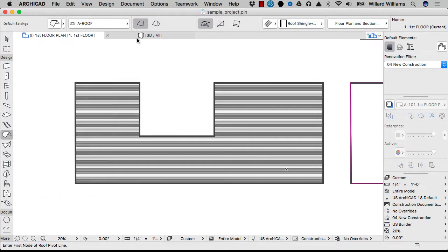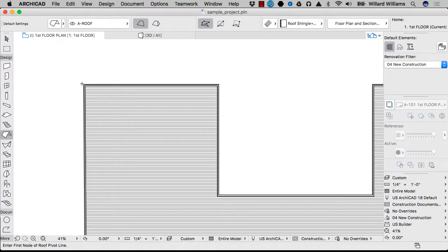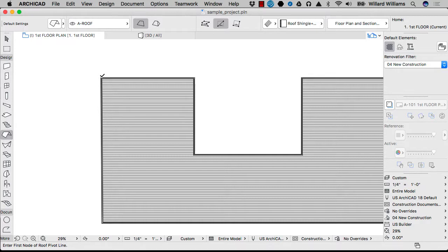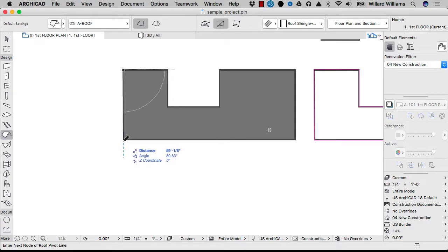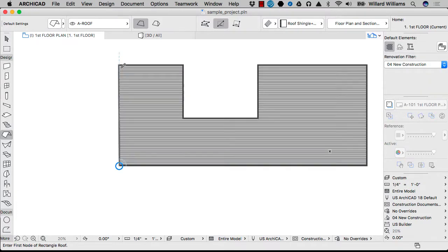So this single plane method, it can work similar to the other ones. Let's just use the 2-point selection. So if I select here, and so the first selection, so I'm making a line parallel to this. This next piece is telling me which side is going to be the high side of the roof. So let's just make this the high side of the roof, and now I can create that edge of roof.